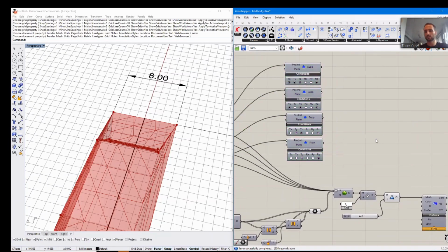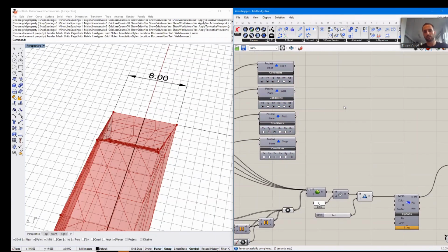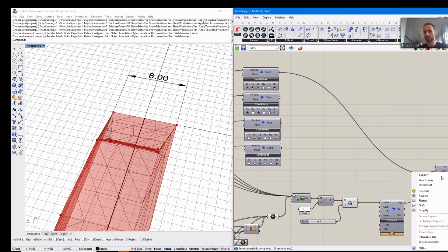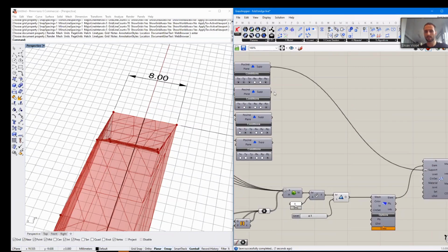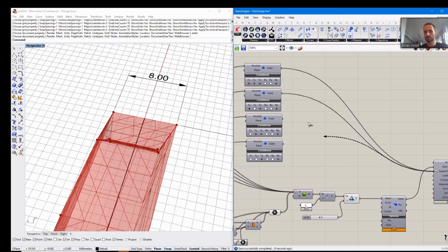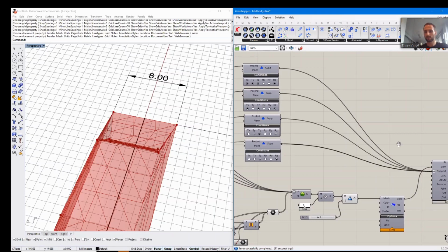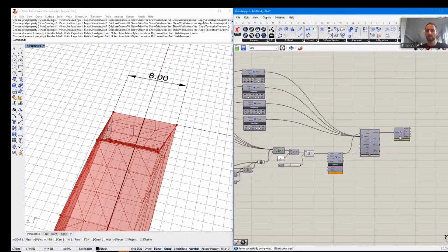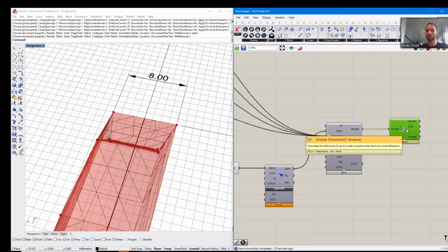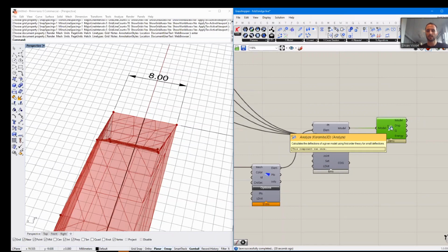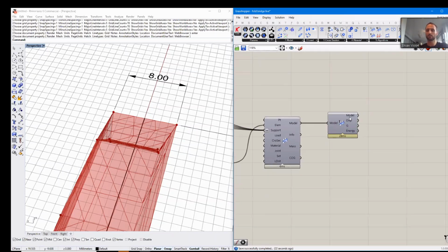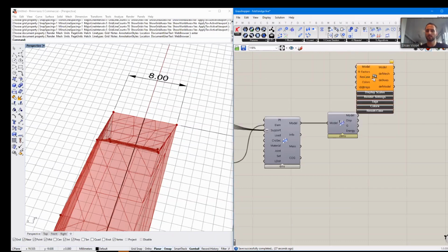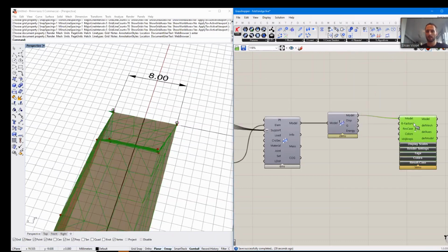And you can also try to make it fixed on all points. Maybe the results will be very similar or even not quite the same. But for now, I'm just making sure this is a nice clean structural setup. And connect all the supports to the support input of the assemble model component. And there we go, we have our structure analyzed already. The component turned from red to gray, and it gives us a valid model output already.